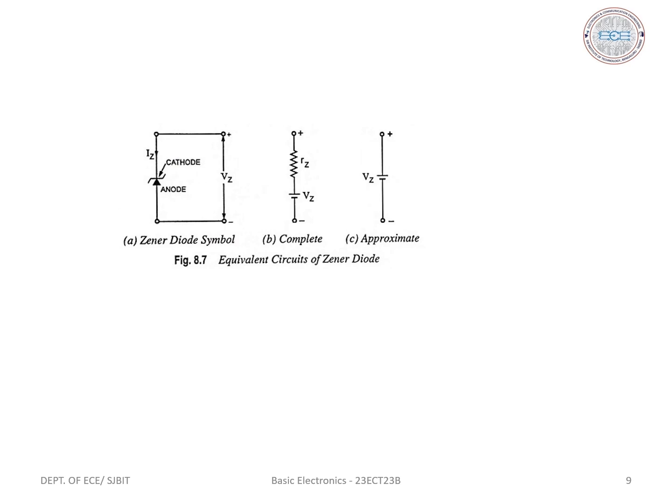Next we have avalanche breakdown. The avalanche breakdown is observed in Zener diodes having Vz higher than 8 volts. The acceleration of the electrons due to the external applied voltage gives them high velocities. These fast electrons by collision produce further electrons. These electrons in turn get accelerated and liberate more electrons by collision. This process is called avalanche breakdown. This results in a sharp rise in current.